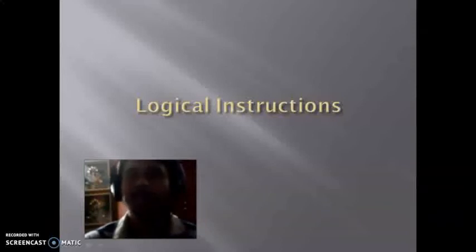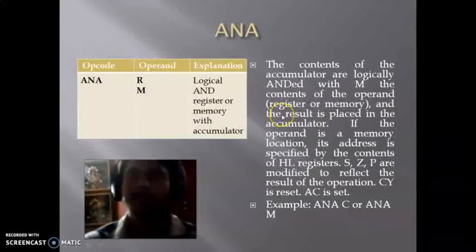I'm going to give a lecture on an important topic, that is the instruction set of the 8085 microprocessor. I'm going to explain the logical instructions. Basically, the first logical instruction is for the logical AND operation, that is ANA R and ANA M.